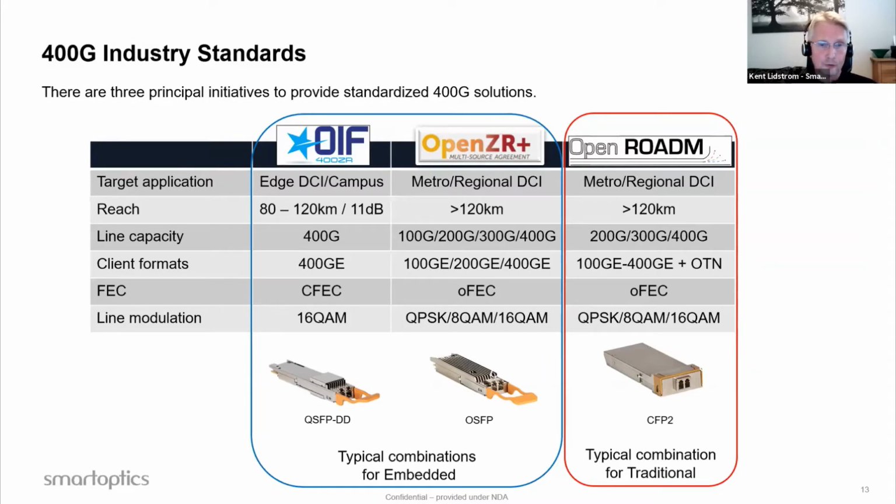The other 2 versions there are designed to be lower cost and also with lower power consumption. So they have a lower transmit power, typically down to -10 dBm. So you need to have a line system built to handle those power levels, and those kinds of systems exist. Our line systems are capable of handling those, so that's not a problem, but it can be slightly problematic if you have an existing network and want to run those lower transmit power formats over those existing line systems.